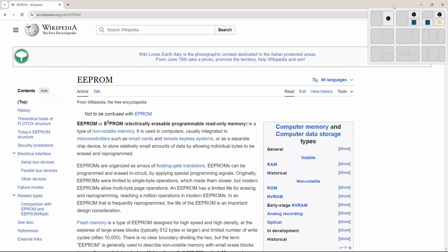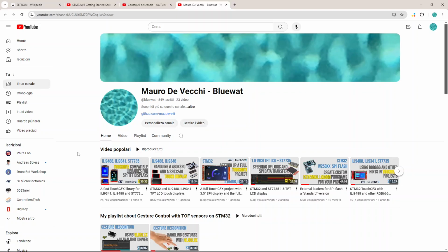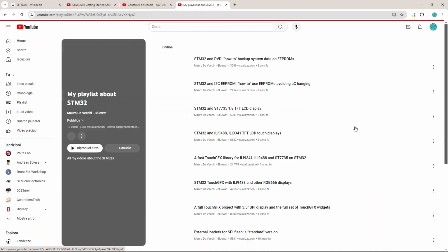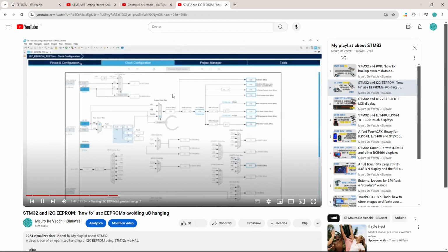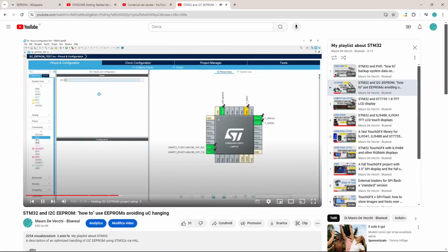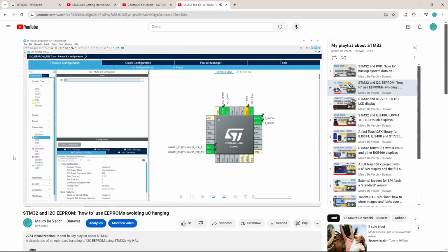We can say that EEPROM is a technology usually specifically adopted to store small information that can change in the project lifetime, and that must be safe powering off the system. When we need this feature in a project, we have to add an external EEPROM to the microcontroller. It is usually communicating via I2C, which has the advantage of being simpler than other ports, needing just two wires, and the disadvantage of being quite slower, which has a minor impact, being involved in transferring small data, as I said.